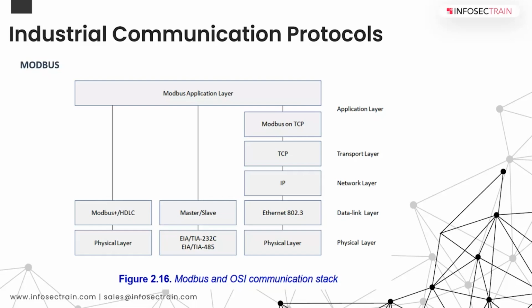So coming back to the protocol here, the master controls the communication and the slave responds to the request. So the protocol is very simple. There is no procedure to connect to the network, no detection of maximum response time, and no diagnosis of the slave status. The basic functions essentially allow words to be read or written from the slave's memory, and the frames contain a function code and associated data. Now you can understand why it is not secure. But yes, there are secure implementations of Modbus also available.